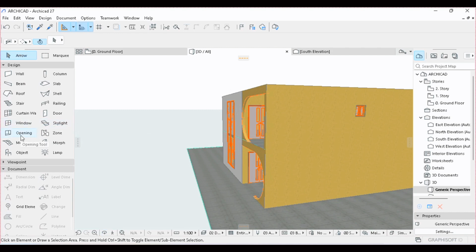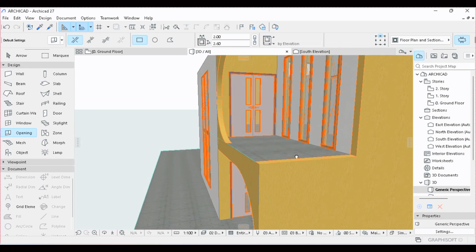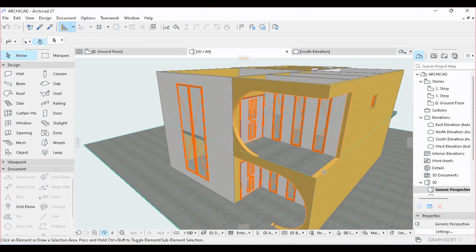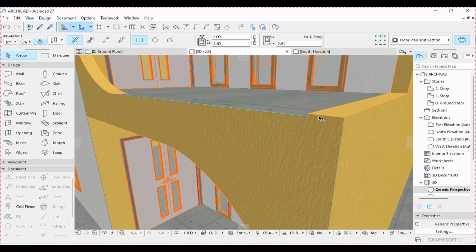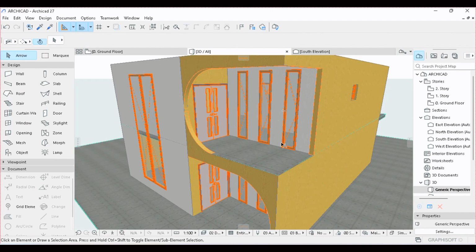So we'll click on openings, and for rectangular openings we are still going to put the same. For the height, I'm going to type in 2.6. And we'll have something like this. So I just love to arrange the rectangle to start from below 261 and put it at 260, so it flushes with the slab.